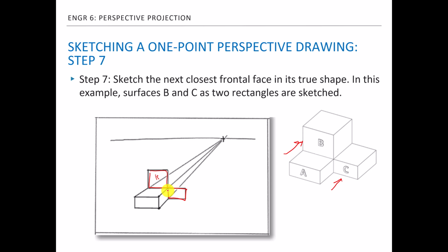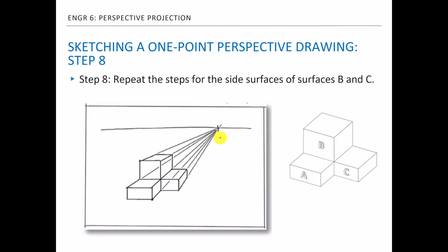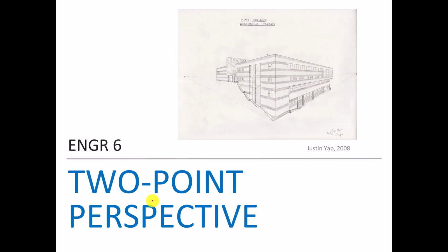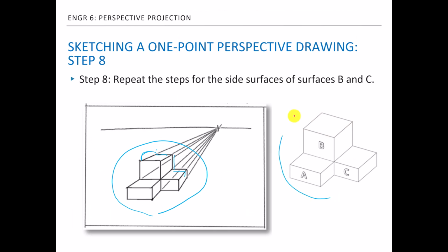Okay, and then you repeat the same thing. So all these lines are parallel to each other, and they are all parallel to my eye direction. So they're all also going to point to the same vanishing point, right? So we'll do the same thing here, and then we'll also cut it by a certain distance. Okay, just eyeball it, cut it, and you're going to make a sketch of this object, right? So that's how we can sketch this.